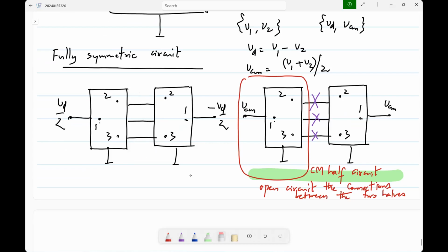0. Okay. So if you have a fully symmetric circuit with anti-symmetric excitation, nodes along the center line, nodes along the line of symmetry will have 0 voltage. So you can just short them to 0 and do the analysis. But this has assumed both linearity and symmetry. Okay. So this part is true only for, okay. So